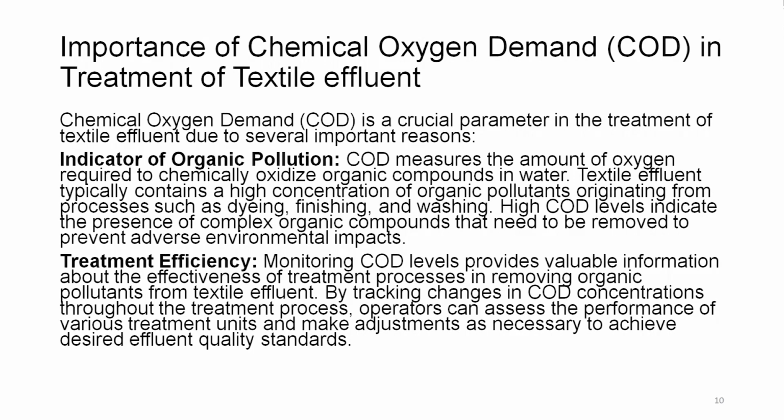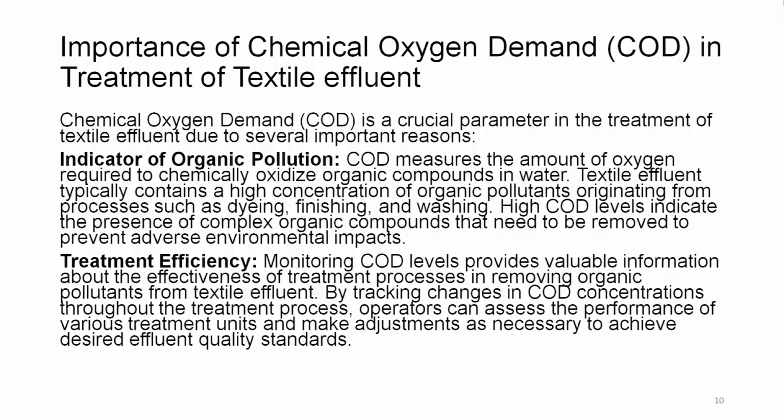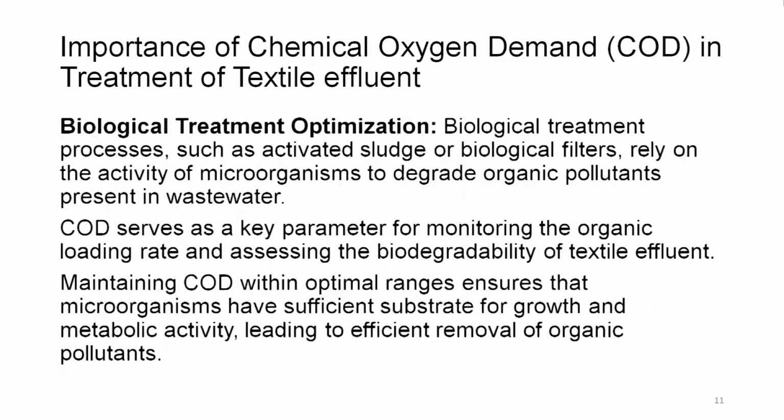So, COD is a very important parameter because continuously it needs to be decreased, and if it is not done so, then one would not know whether the treatment process is effective or not.